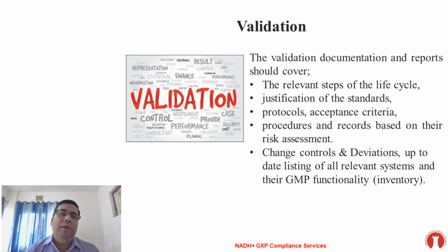There is one question: if risk assessment is performed by the vendor, then should risk assessment be performed by the user department, not for new instrument qualification? Mr. Satish has asked me this question. I want to tell you that risk assessment or quality risk management should be performed by the user. If the quality risk management is done by the vendor, no problem, but you should have a procedure to evaluate that quality risk management, whether it meets your requirement or not.